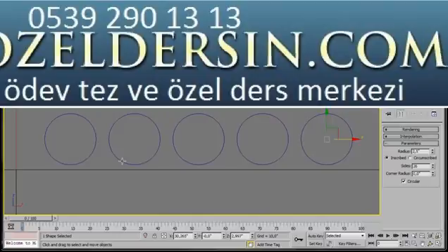We're going to select the second one on the left-hand side. Now we can pop over to the Modify panel and set the radius to 1.5. We're just going to leave the sides at 26. Let's select the next one along, and we're going to do the same. We'll pop over to the Modify panel and type in 1.5. Also, we'll do the same for the next one, 1.5. Let's select the last one now, and the radius, we're going to set it to 2.4.